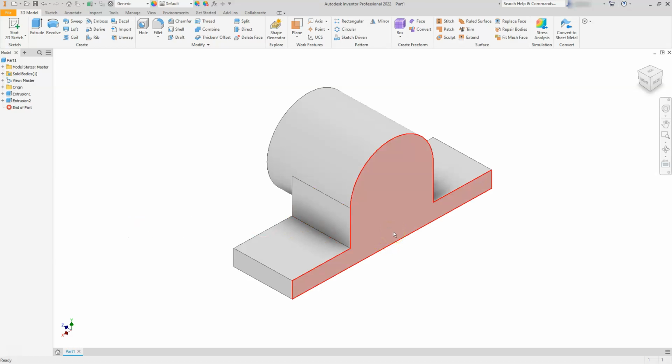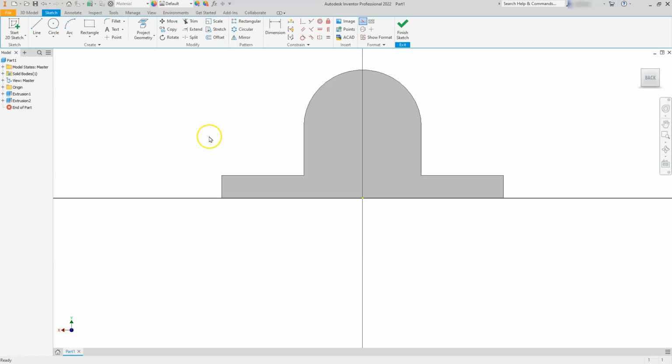Let's go ahead and create another sketch along this back face. So I'm going to select this face. I'll select the little plus here on the side. I'm going to project in these two lines and that top arc. Let's go ahead and draw a line from this endpoint. And then if I kind of go along this line, you'll see that I will get a tangent mark. So go ahead and select tangent of that arc.